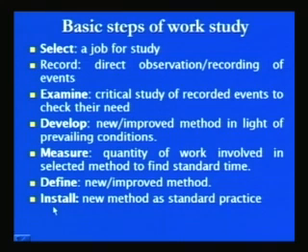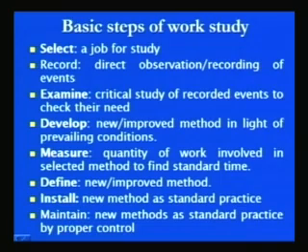Once the things have been defined, they are installed in practice. So, the new method is installed as a standard practice by allocating all the resources needed for carrying out the job by the new method. Maintenance is required because people have a tendency to go back to the original method. That is why the newly installed method should be checked frequently to see whether the new practice is being followed properly or not, and that is done by the maintenance step of work study.